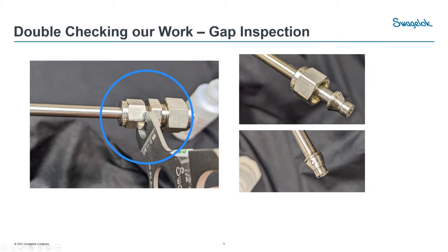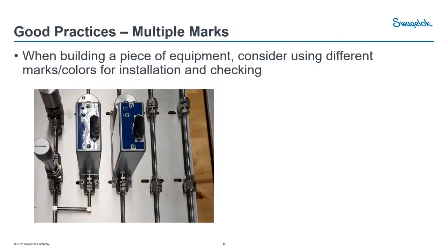You see a little gap between the back ferrule and front ferrule, nice conical shape, and that's about what we expect to see. Well, this one I way over tightened intentionally. Then when I reinstalled it, it wasn't able to be tightened enough or correctly to prevent the leak. So you can see the ferrules are crushed together. There's a little bit of deformation of the ferrules there, a lot of shininess on the material. So again, I was able to diagnose it, but it also shows the gap gauge isn't necessarily always the last word in it. It will tell us if we installed it correctly the first time, but it's not necessarily going to tell us down the line that we've tightened it up enough to prevent the leak.